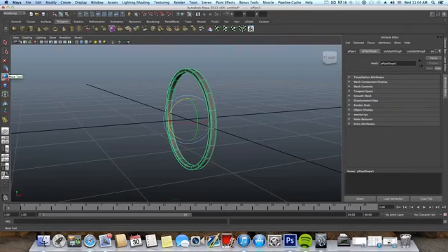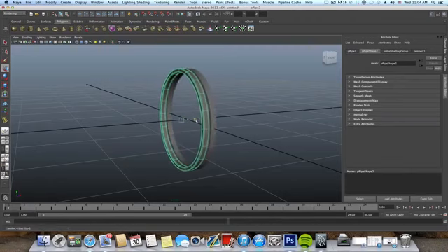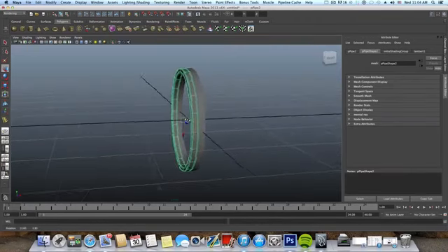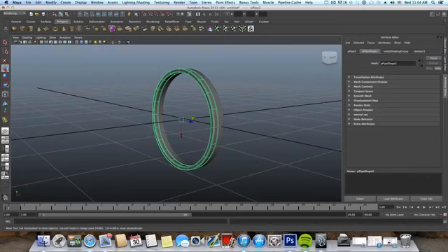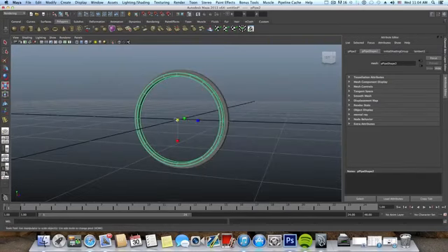We're using Shift D, and I will show you in a second what it means. You will first switch to the Move tool, Shift D, and move the object over here to about so. Okay, and you want to scale it also at the same time, so we create some kind of cone.